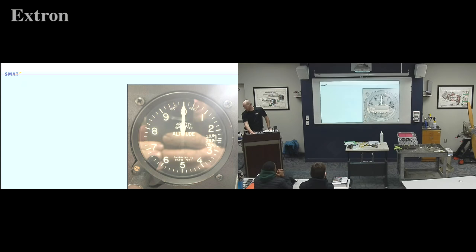This is a fun one. Setting the altimeter to 0. Everything is zeroed. That's going to tell me my actual pressure. So if I set it to 0 and read my Kollsman window, it'll tell me what the air pressure is where I'm at right now.